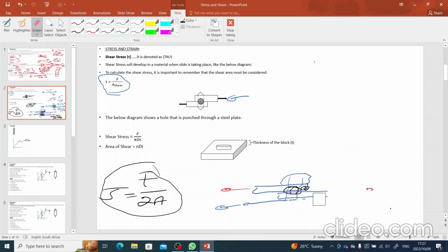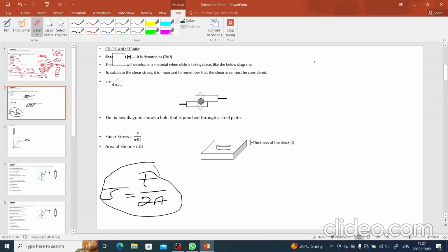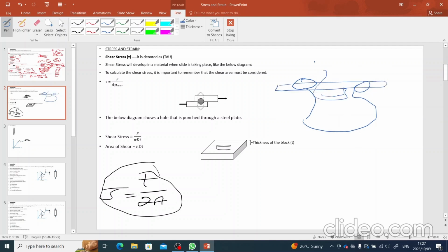Now, we shouldn't limit our double shear to that diagram. Let's give you another diagram. Some of you did work with this diagram when you were doing your N4. You have a shackle. This is my funny shackle. Then there's a pin in here, and a hook on that shackle. Then it is tied to a rope, and it experiences the normal force, the upward force. Now you would realize that this pin will experience a shear here and a shear there, since they are pulling this material upward.